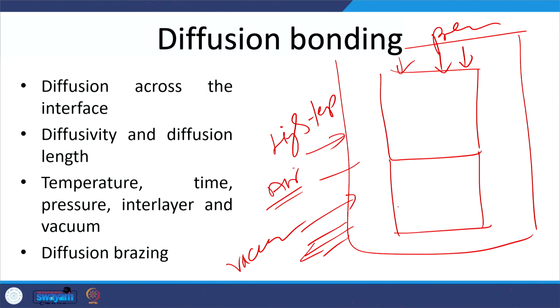When vacuum is created, this chamber will be free from any kind of oxygen, nitrogen and hydrogen. So, when the heating is done in vacuum where there is no oxygen, nitrogen or hydrogen, it will keep the surfaces clean, and they will not be affected by the interaction of the metal with anything else, because there is no other kind of gas which can form some kind of compound at the interface and resist or interfere with the diffusion.